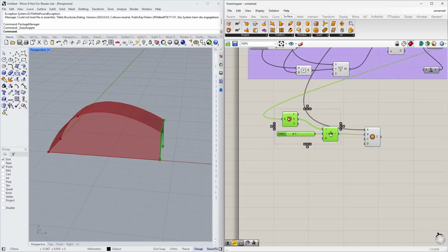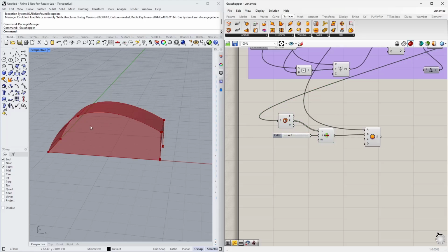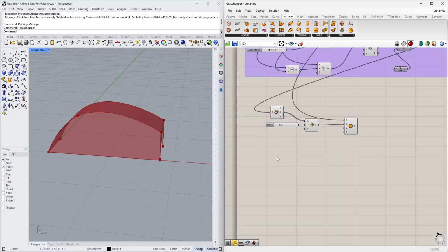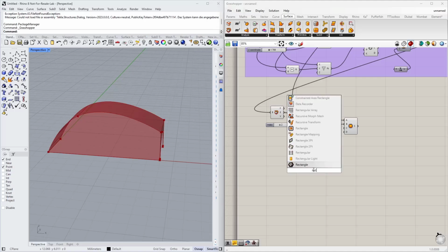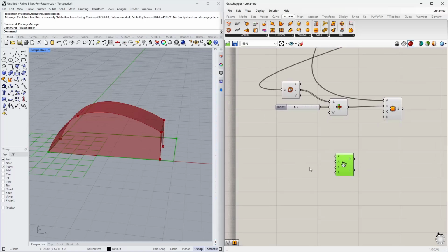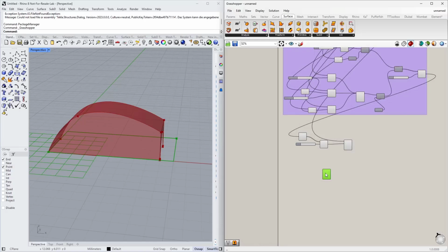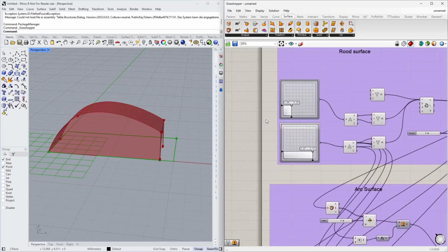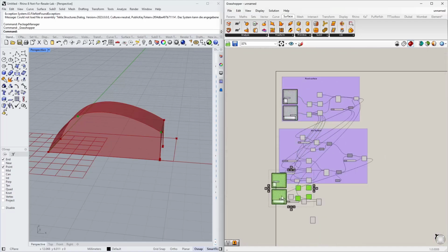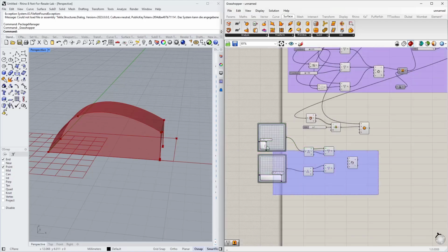So far so good. Now I need to cut out a rectangular hole in here. Same logic as before. I will create the rectangle in this case by 2 points. Yeah, the 2 points are A and B. And then I extrude the rectangle and then cut it again from the original surface. These 2 definition nodes of the rectangle can or shall be defined again via an MD slider. So I just copy some of those things here, copy, paste, and I will reuse it down here.